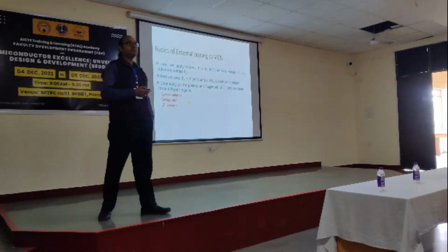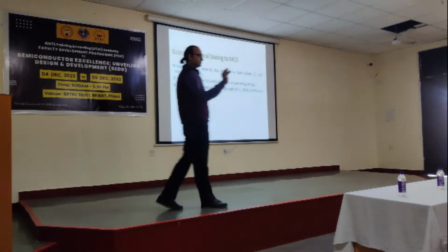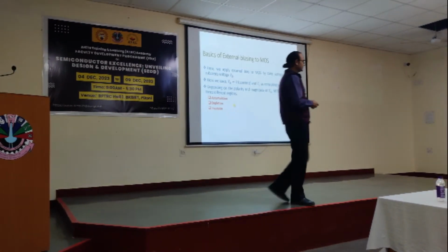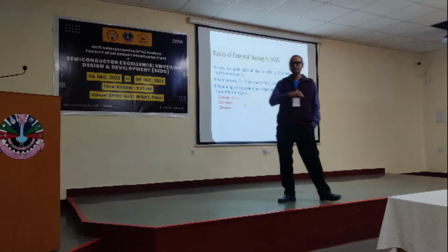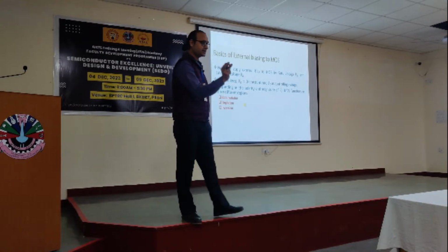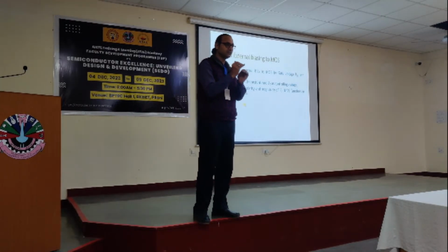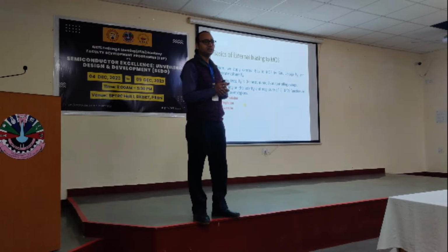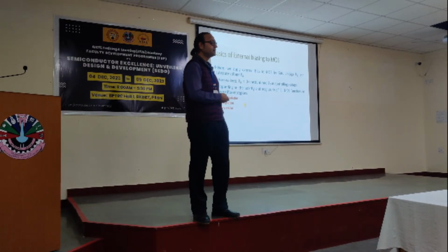Okay, but before that we have flat band voltage also. The gate voltage required to make the bands flat in the semiconductor is called flat band voltage. So for the threshold voltage, the threshold is to invert the channel. The first part is flat band voltage.